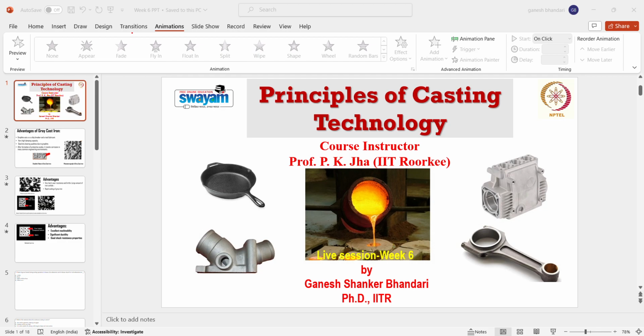For example, if we add copper into your steel system as an alloying element, what will happen when you pour it? That copper is going to solidify first, due to its low melting temperature, and you will get the foreign particles to start the nuclei formations.